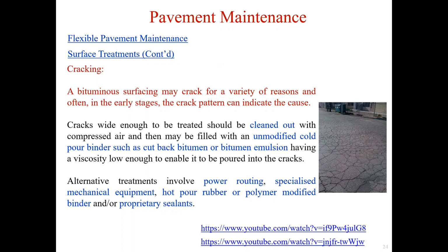It is important that the initial cracking be investigated so that appropriate remedial action is taken later. Neglecting cracks will lead to accelerated cracking and other types of pavement distress. Sealing the cracks prevents further weakening of the pavement.